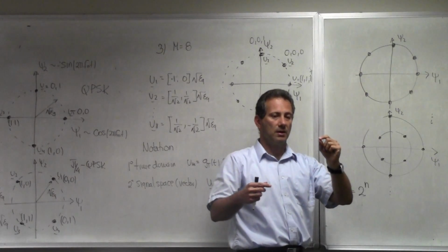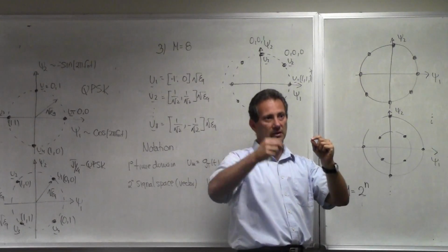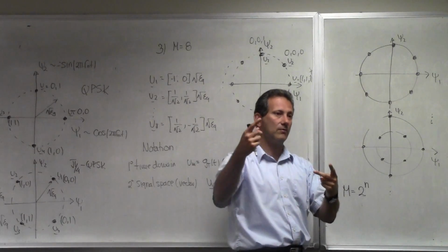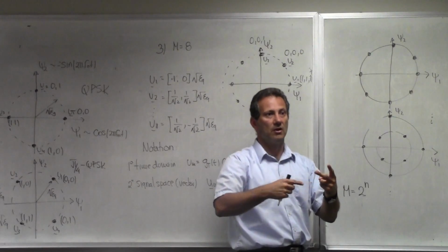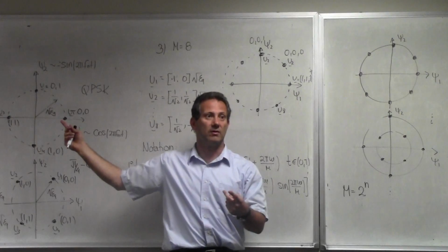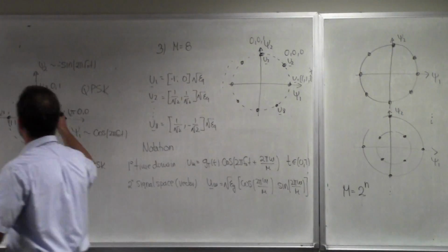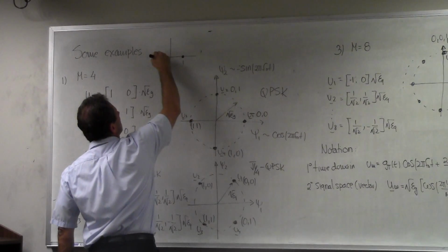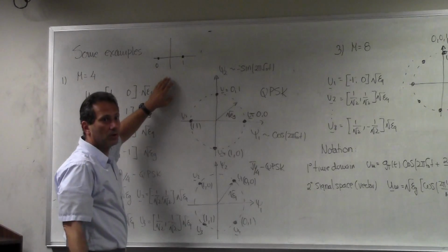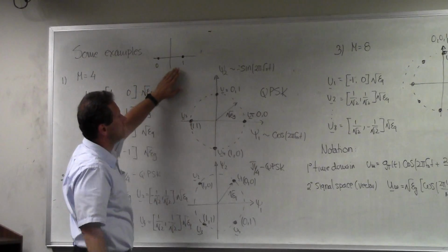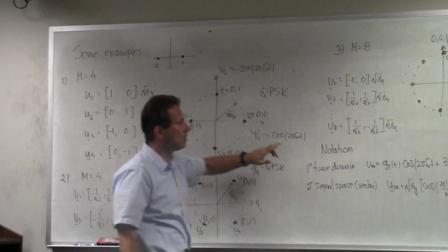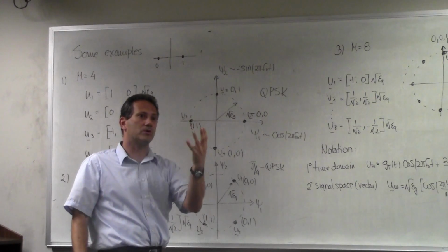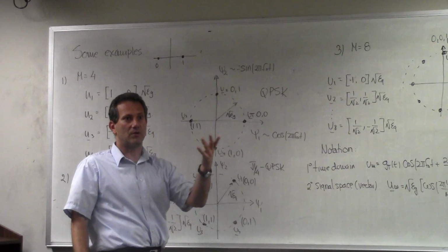Say you pick one, then you send one waveform, and the 0 comes, you send the other waveform. You're talking about just 2 waveforms that you use in signaling. One waveform for 1, one waveform for 0, right? And you end up with what we call PSK, where the constellation in that case, how would it look? You would pick, let's say, this one for 1 and this one for 0. But this is a one-dimensional signal. Now, if I encode 2 bits at a time, then what can happen? I can have 4 possible combinations: 0 0, 0 1, 1 0, and 1 1.